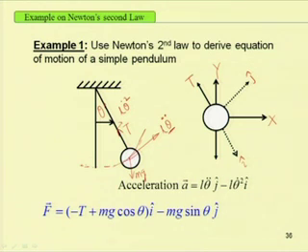So, this is subjected to a force T, that is tension, and mass m, and this mg force, mass into acceleration due to gravity. The mg force can be divided into two parts. One is tangential to the path, and the other one acts along this direction. So, this is equal to mg cos theta, and this term is equal to mg sin theta.